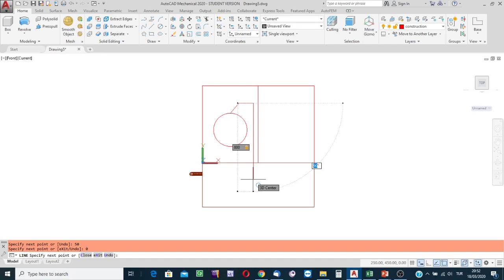Right angle as negative, minus 90. Press enter. Yes. Okay. Then press escape button. Restart the line drawing process. In this example, the other boundary line starts from this midpoint, and it is extending in the down direction. This is just an example.